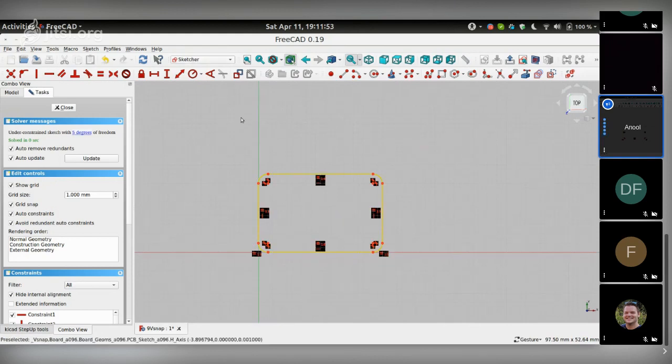So the sketcher tools allows you to make a new sketch. To start with, since I want my pentagon to be centered around this existing rectangle, I'm going to draw some reference construction lines. That is done by highlighting this tool, which changes all of them to construction lines, like so.